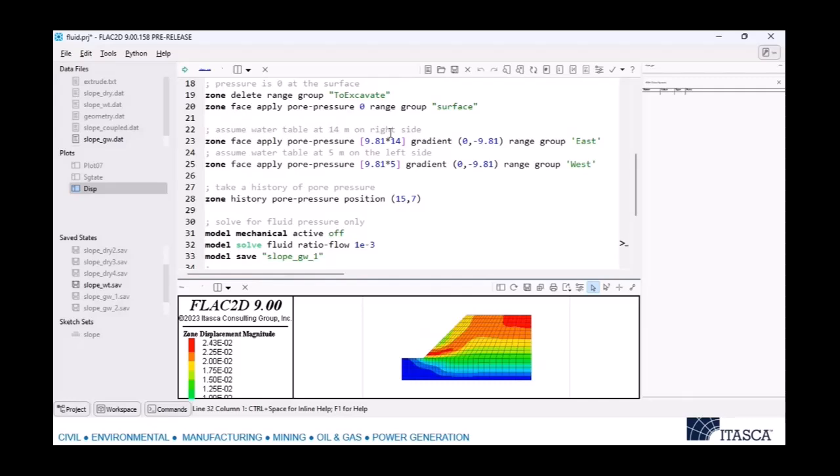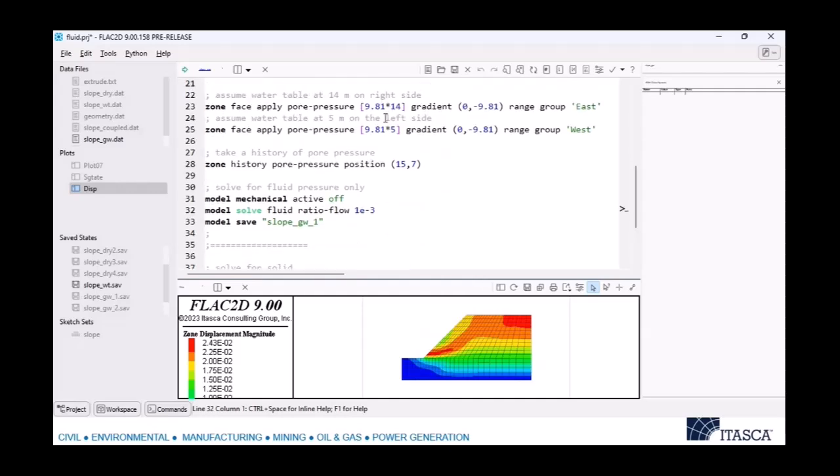So it's basically saying the inflow over outflow, right? If everything's in full equilibrium, the inflow and outflow match perfectly. This is saying that it's allowed to be 1e-3 off in ratio, and we'll call that close enough, okay? It's an imperfect metric, but so are all of them.